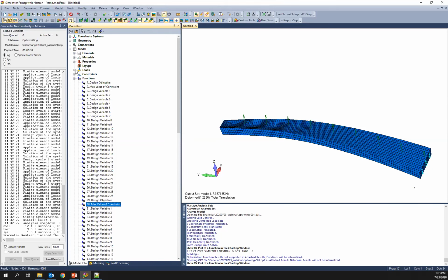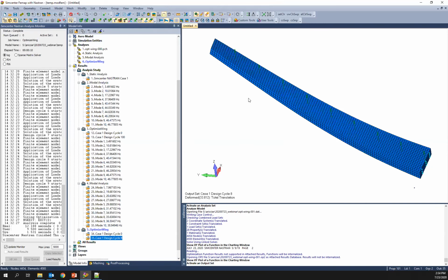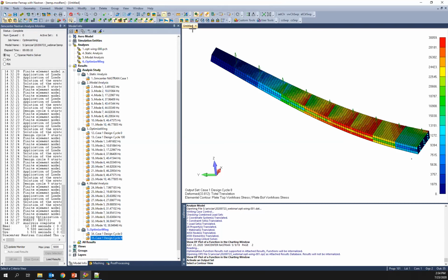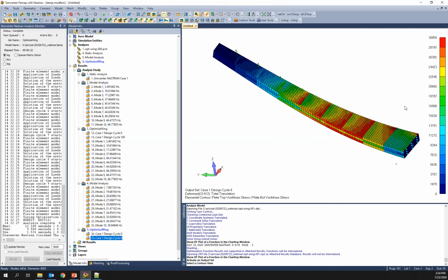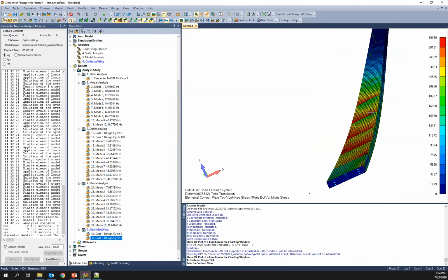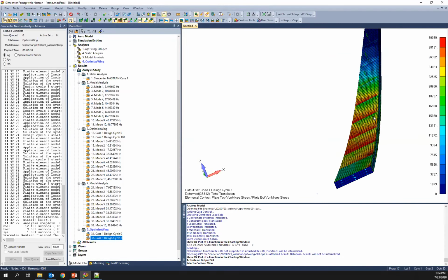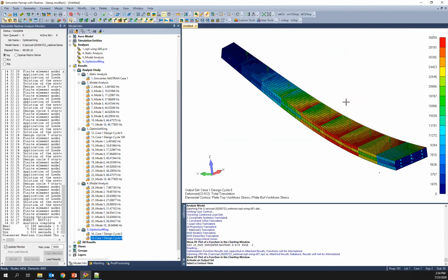So it looked like that second run finished. So let's check that. That ran fairly quickly. So we have design cycle 8. And here what we see is, since we didn't have that modal frequency constraint, we know the stress constraint needs to be active, because that's the only thing that's keeping the optimizer from removing material, and it is. So we have 30 KSI and some tolerance. We see it's optimized each bay so that, at least in the top skins, we're hitting maximum allowable stress. So this is sort of what you'd expect.